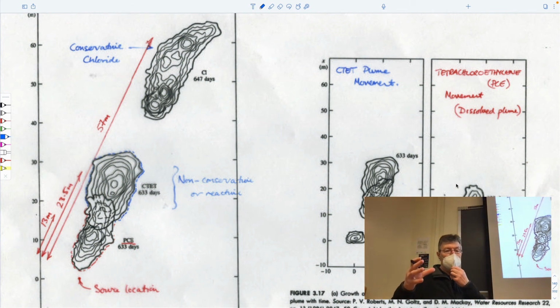So it would sample some heterogeneity, but because the flow regimes that we set up have their own geometric dispersion in them, the results we get are completely swamped by that geometric dispersion, and therefore the dispersion we measure isn't really representative of the behavior of the aquifer. And so those are no good. And so what we'd like to do is use an experiment that tests it at a big scale, and also at the kind of flow rates that we expect to have in the field in our real system.